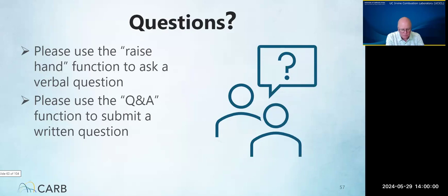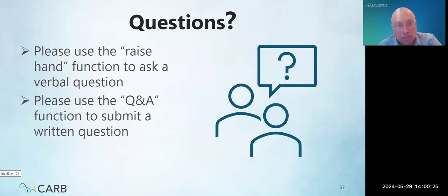The CARB CHC program is also currently actively working with the United States Coast Guard District 11 headquarters officers regarding an operational protocol for allowing a CARB verified DPF system to utilize a bypass if necessary. This will be incorporated into the executive orders that will be issued for CARB verified Level 3 DPFs, and would include operating protocols and reporting protocols for how the bypass is operated.